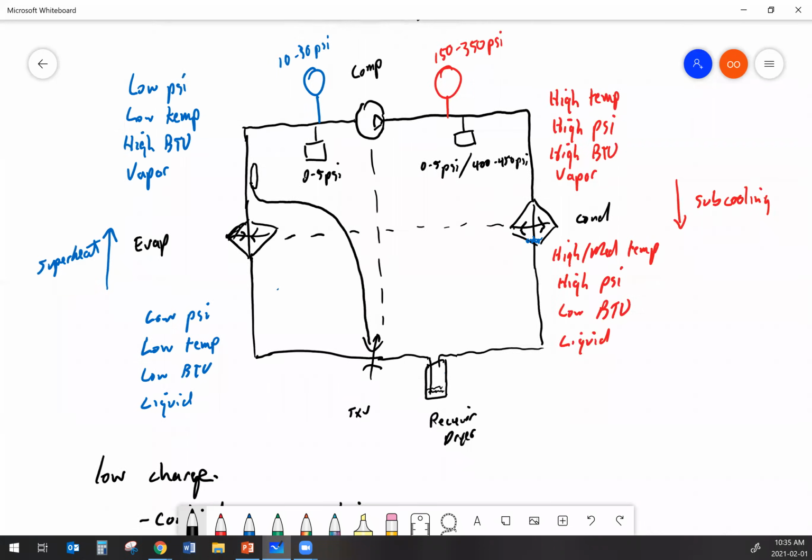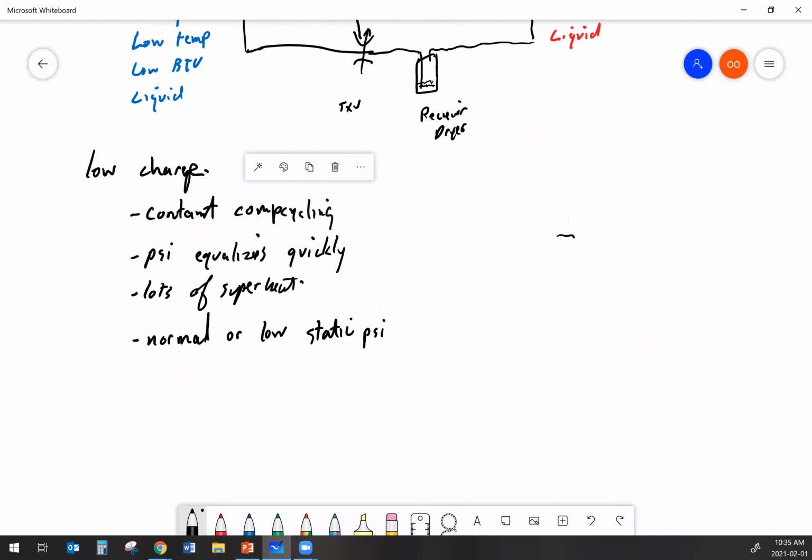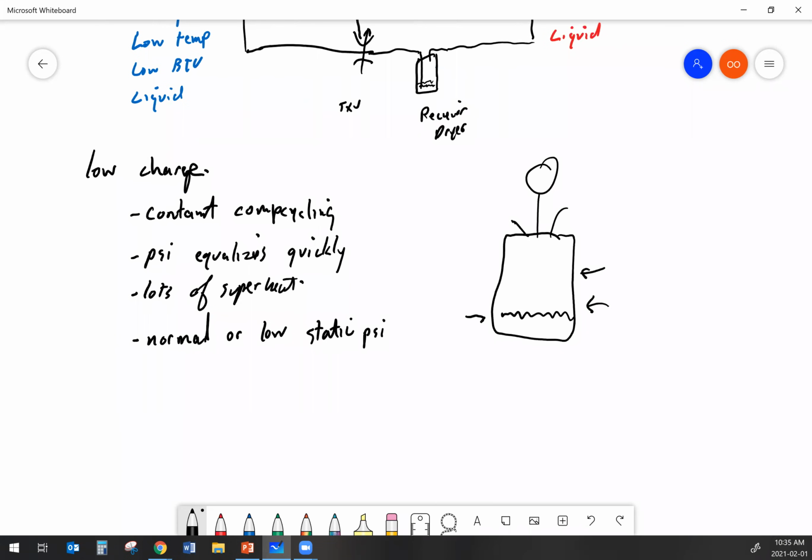Static pressure is developed because when it comes to refrigerant, and you have that refrigerant in an enclosed container, and you put a gauge on it, if there's any refrigerant in that enclosed container, your gauge is going to read some pressure because ambient temperature put heat energy into that container. The refrigerant boiled and it turned into vapor, and that vapor builds a certain amount of pressure. And once the pressure builds up to the point where the pressure temperature relationship gets to what's called a saturated pressure, now the refrigerant stops boiling, the pressure stops rising, and you end up with static or saturated pressure.